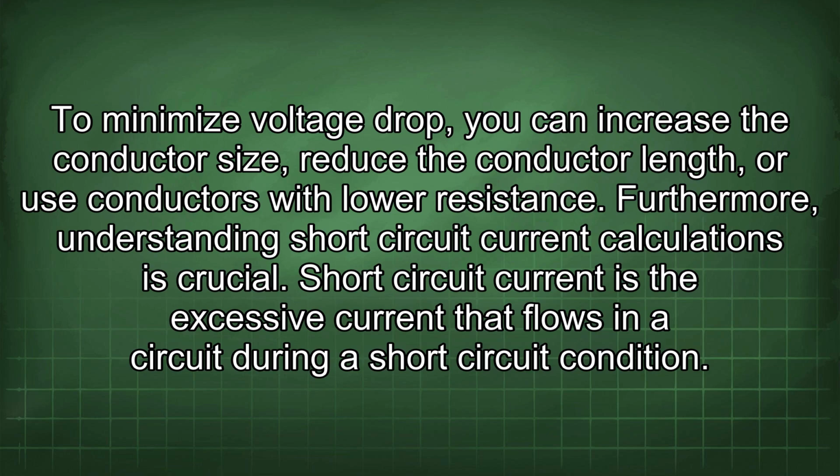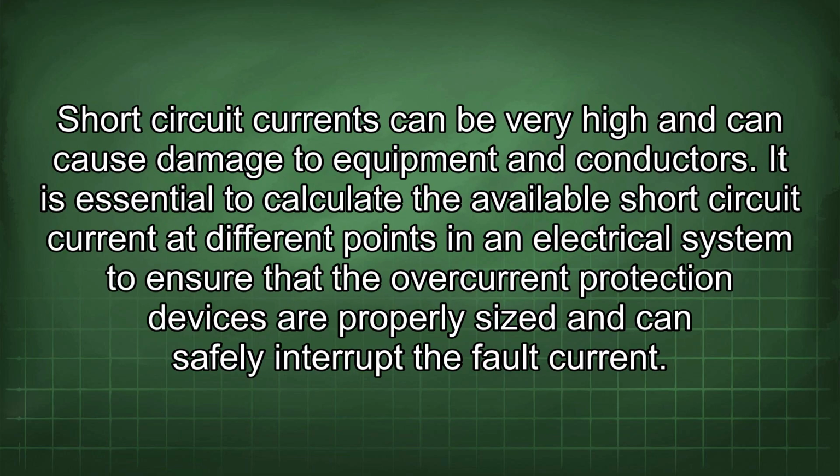Furthermore, understanding short-circuit current calculations is crucial. Short-circuit current is the excessive current that flows in the circuit during a short-circuit condition. Short-circuit currents can be very high and can cause damage to equipment and conductors. It is essential to calculate the available short-circuit current at different points in an electrical system to ensure that the overcurrent protection devices are properly sized and can safely interrupt the fault current.